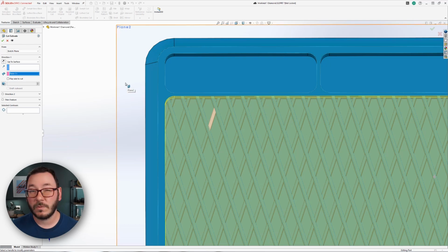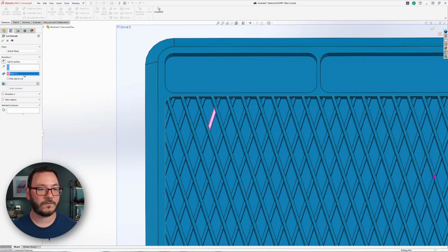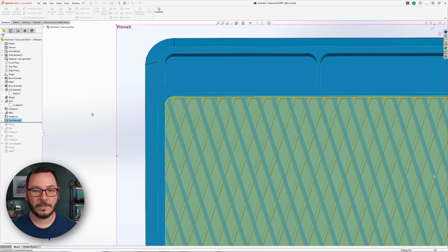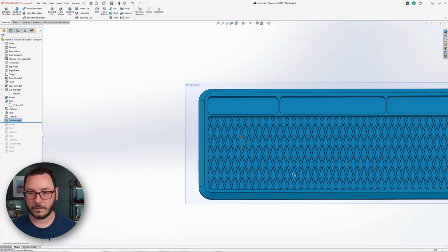Right now, maybe the plane would be a smarter reference, right? We're referencing an individual face here that could potentially change, especially one that's this far out. If you decide to change the spacing of these and suddenly this finds itself wandering off and is no longer an instance anymore, maybe it's better to point it to a different reference. Again, that will be up to you as you're using this method. But the point is we can use an end condition again to reference that height. So if we reference the height of this plane, that's the height that sets the level of the other set of ribs. So we will be using that level to pull these back down from the top and clean up this geometry. There we go.